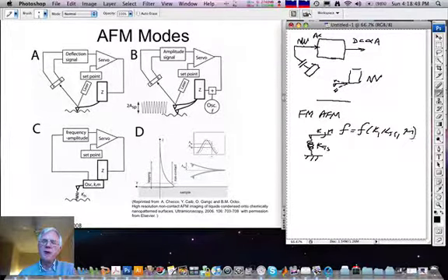And so by setting the tip into oscillation, by providing positive feedback in the servo loop, and then measuring the frequency of resonance and adjusting the height so as to hold it at some desired frequency, an image can be made of the surface again. The reason for the extraordinary sensitivity of this mode is as follows. In detecting an amplitude of oscillation, one can make this measurement to perhaps a few percent.